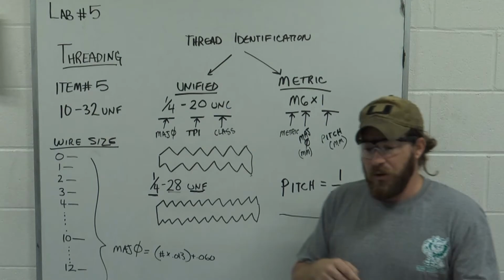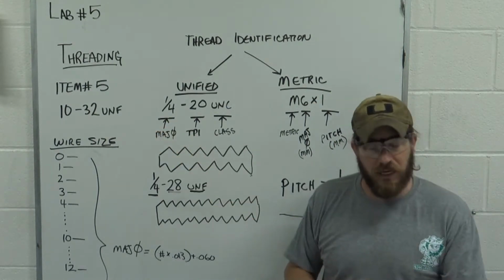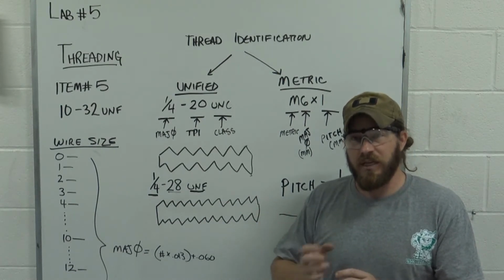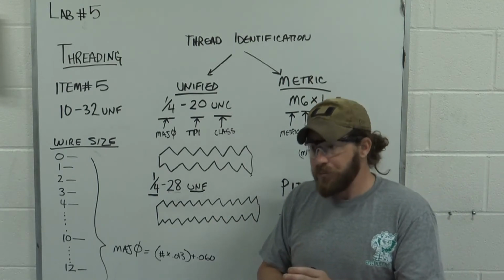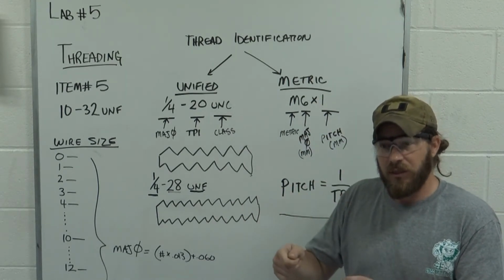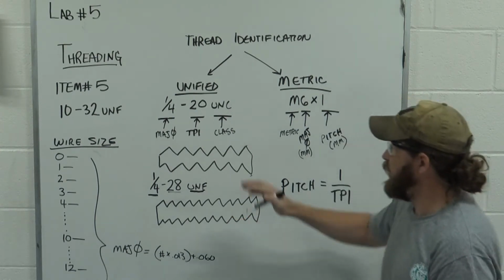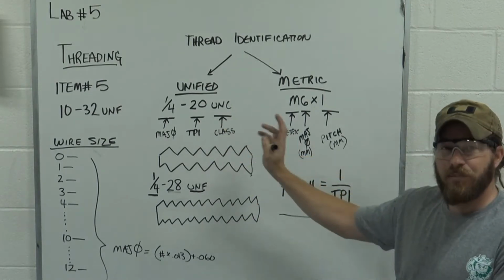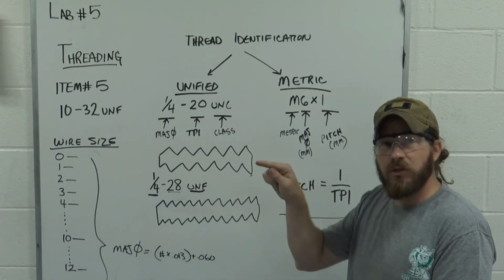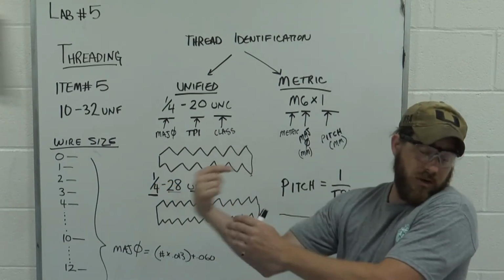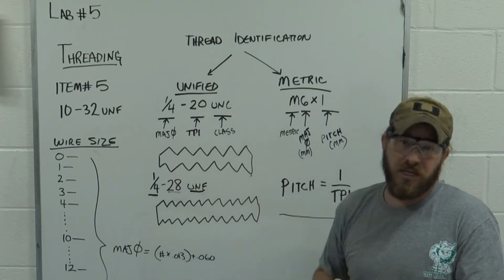So that way, when we're making precision tools like the lathes and the mills that we'll get into, if we grind in these and make really nice threads, and we can really control the pitch, each full rotation of that thread will translate that thread. So if I had a precision ground quarter 20, if I turn that bolt one revolution, it would go in or out, depending on which way you're turning it, 1/20th of an inch.